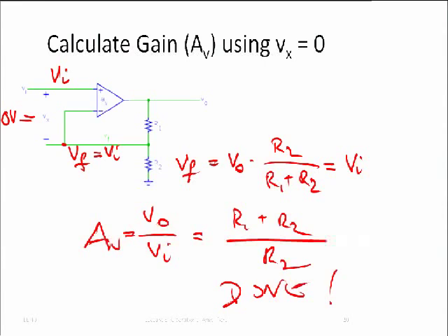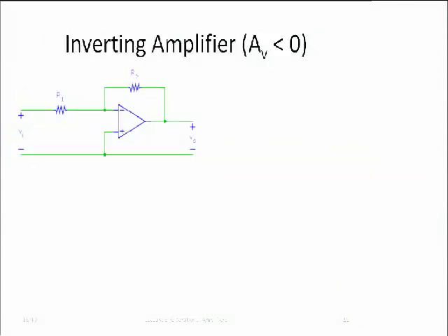Okay, by knowing this, we managed to solve this problem trivially and very, very quickly. Remember this, right? When you solve for voltages in op-amp circuits, look, is there a negative feedback loop? Yes. Well, in that case, find out where Vx is in your circuit. Vx is 0. Use that in analyzing the circuit. We'll do now a bunch of examples of this. Okay?